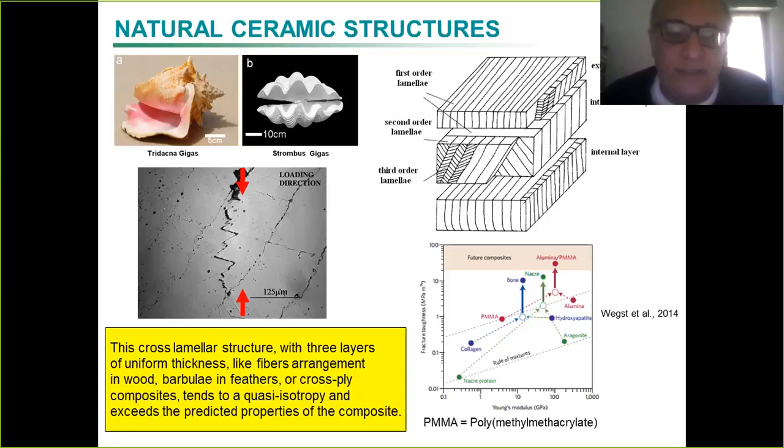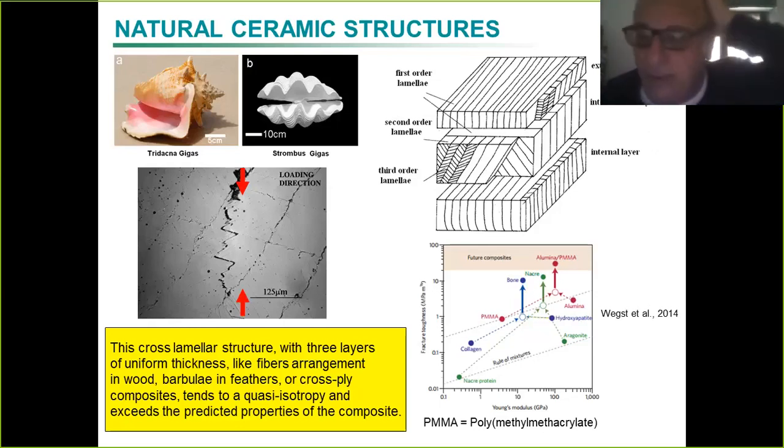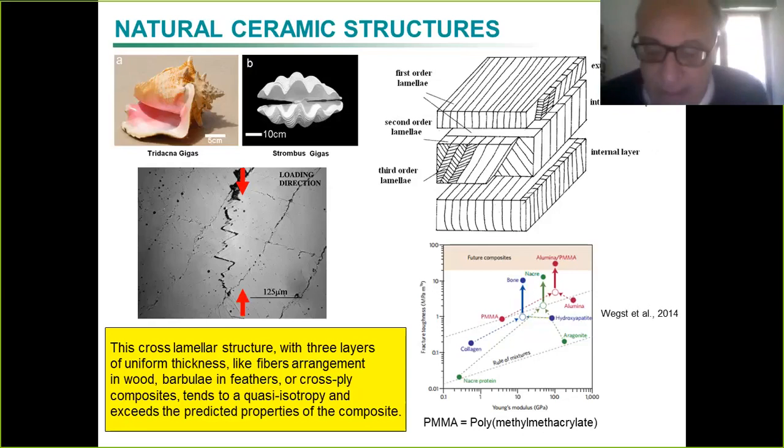Even if there is a loading direction, which might be compression, they are able to withstand a little bit of tension, but even if there is a very strong compression, they are able to stop the growth of the crack in that direction. This is a very important problem, for example, for cement, concrete, and stone, and building materials, even in clay bricks.